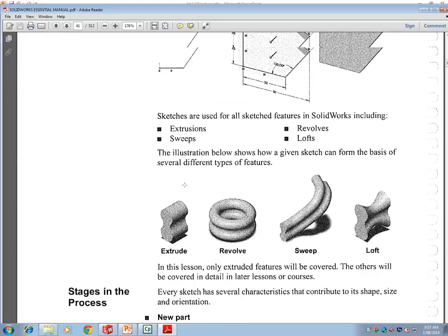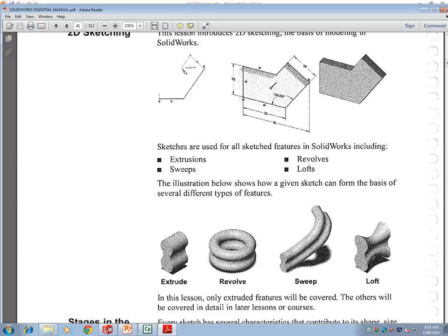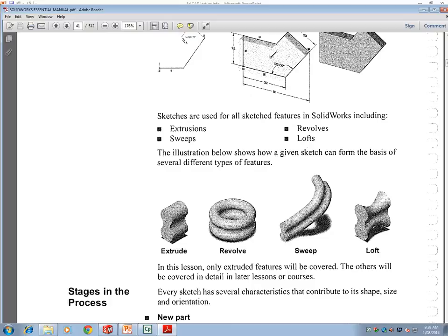See what is happening once the sketch is drawn, where we are heading basically is using some of the features being displayed here. A basic extrude, a basic revolve, and sweep and loft function. See, these are all based on the same sketch. The sketch you can see is two ellipses being joined, but they have been used differently in extrude, revolve, sweep, and loft.